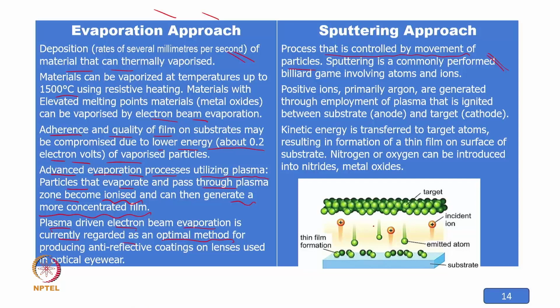So similarly, there is a stick and they are trying to direct the balls to the right place where it should come, and then go for the densification of the coating. And again, in this case, different gases have been utilized. The first case is argon, where argon gets positive ions, and it gives a direction and moves the emitted atoms directly so that they can go and form the layer on the substrate.